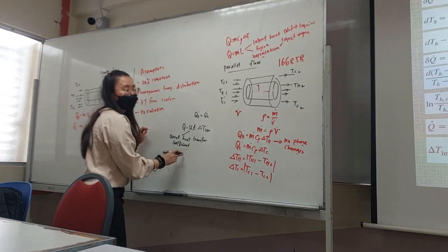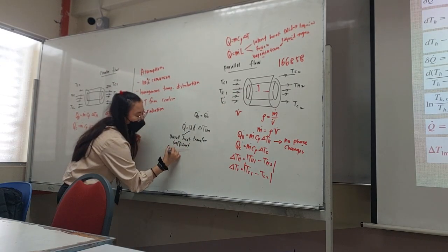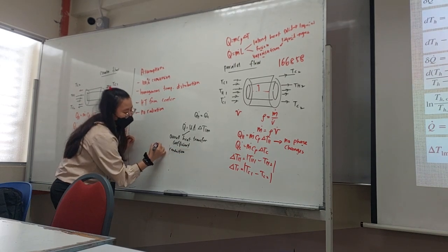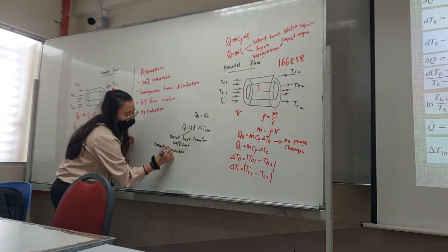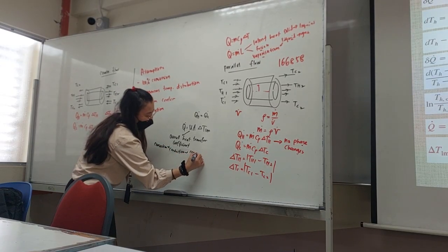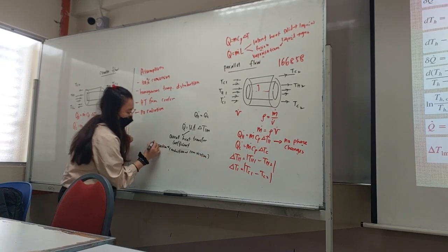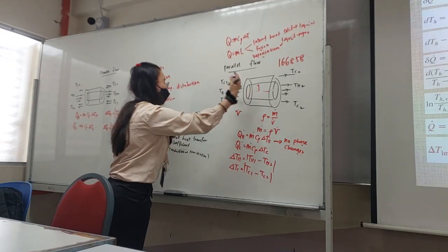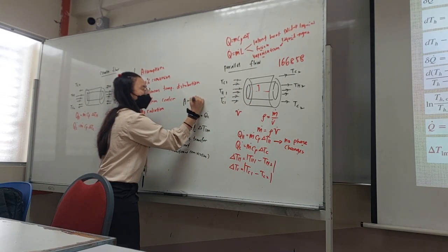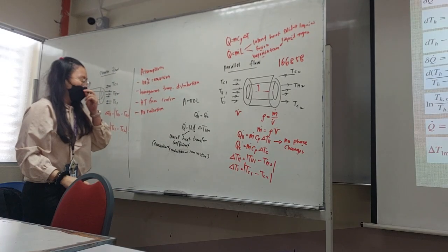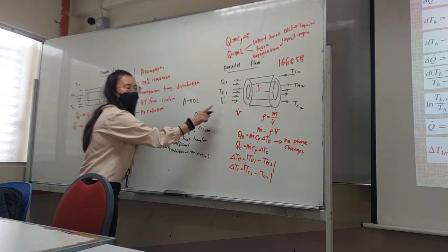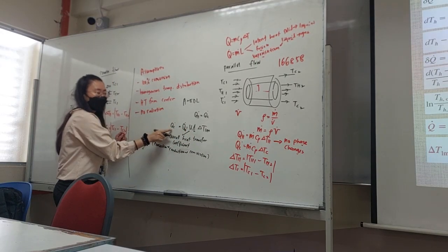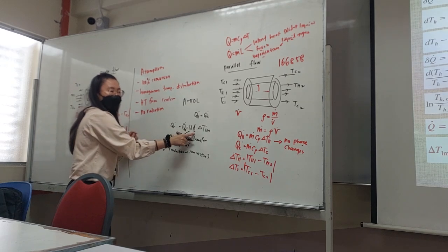So the overall heat transfer coefficient includes conduction, convection, conduction, convection. The area here is the cone, so the area you are using is pi D L. Since it is 100% conversion, this can be QH or QC, so Q equals U A delta log mean.